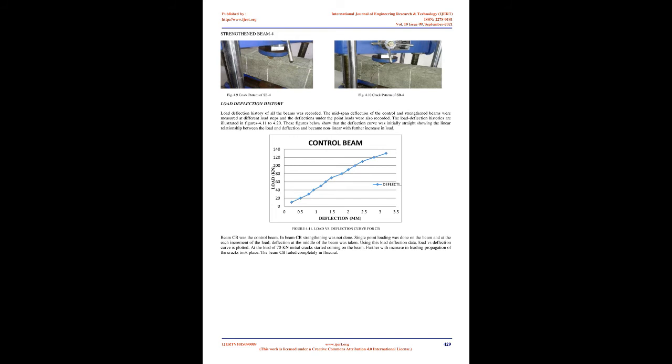After their uniform mixing, the fabrics are cut according to the size, then the epoxy resin is applied to the concrete surface. Then the CFRP sheet is placed on top of the epoxy resin coating and the resin is squeezed through the roving of the fabric with the roller. Air bubbles entrapped at the epoxy/concrete or epoxy/fabric interface are eliminated. The composite laminate was attached starting at one end and applying enough pressure to press out any excess epoxy from the sides of the laminate.